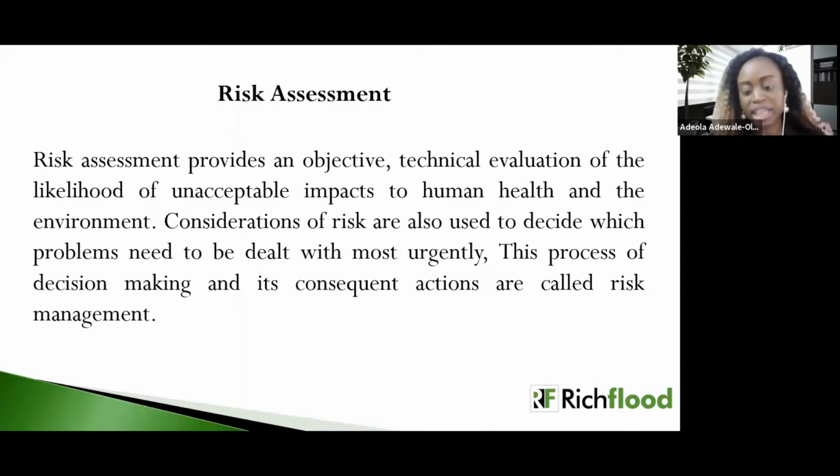And also, we say a risk assessment has to do with making judgment on the tolerability of the risk on the basis of a risk analysis, even while we are considering the influencing factor, that is risk evaluation. Now, the risk assessment of contaminated sites depends fundamentally on the data that is available about the characteristics of the site, including contaminant sources, pathways, and the potential receptors that may even be at risk.